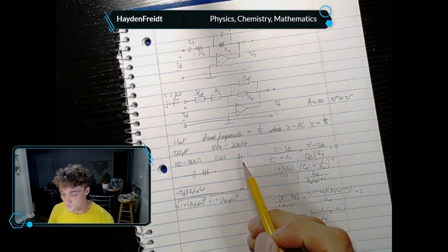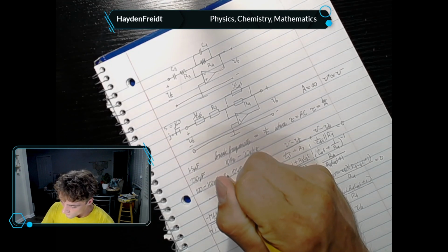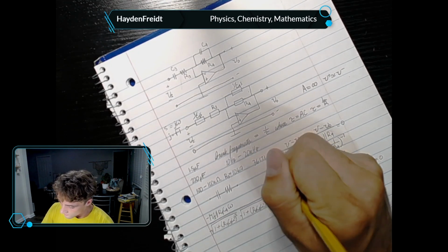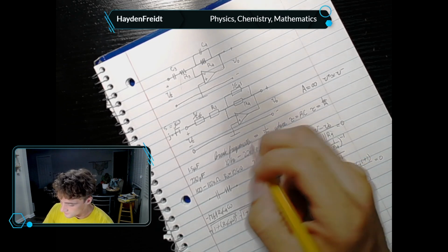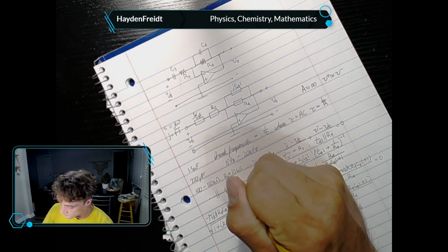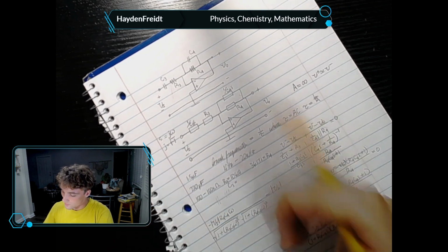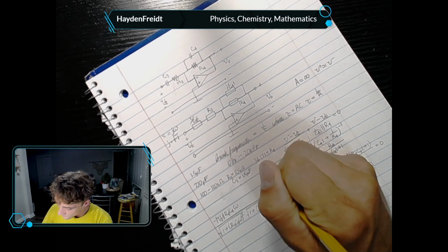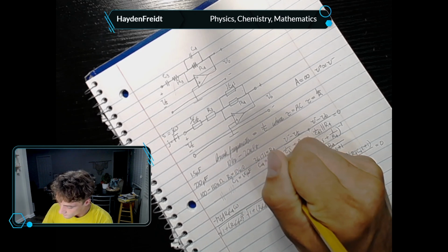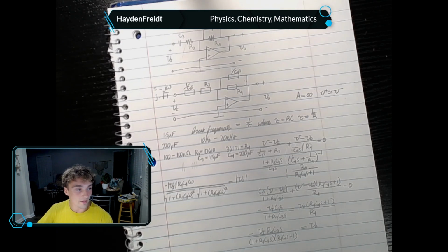So this is continuing from the last problem. These are the values of our resistors. And now this is R3. R3 equals, this equals R4. Okay, so that means C3 equals, here, I'm going to get rid of this. That was not applicable. That was a dumb route. C3 equals 1.5 microfarads, and then C4 equals 220 picofarads. Okay, now what is the mid-band gain for this circuit?